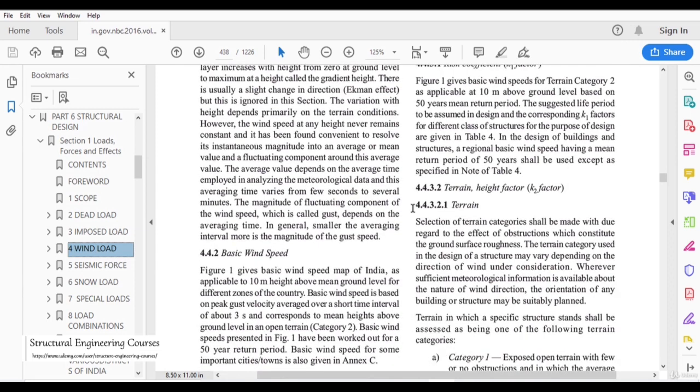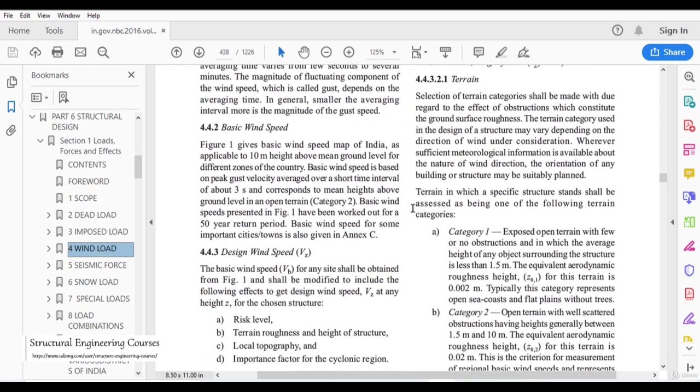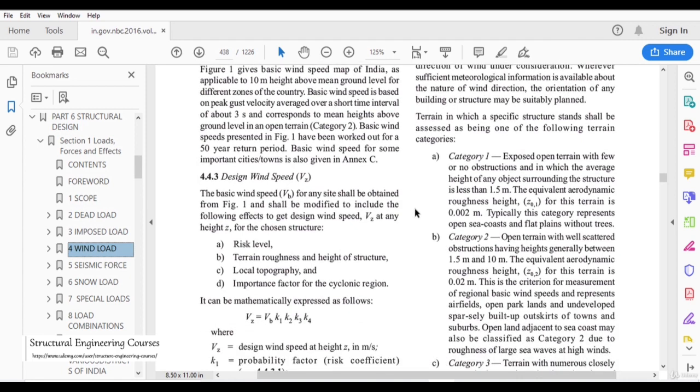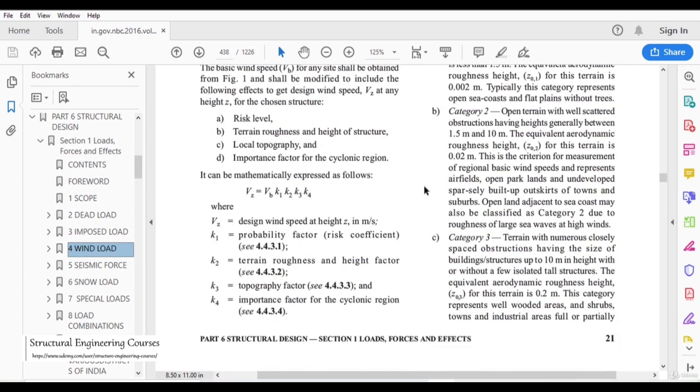So more or less the approach is same. That is, first of all we consider some wind speed, and after consideration of that wind speed, we need to assign some coefficients. We need to multiply this wind speed with some coefficients, and accordingly for various shapes the country code gives us various coefficients for the calculation of the final wind load values. I shall take only 10 minutes of your time in explaining all of this, because otherwise if I went into depth of explaining each and everything, then the length of this video shall be more than 1 hour. So consider it just as a short briefing.